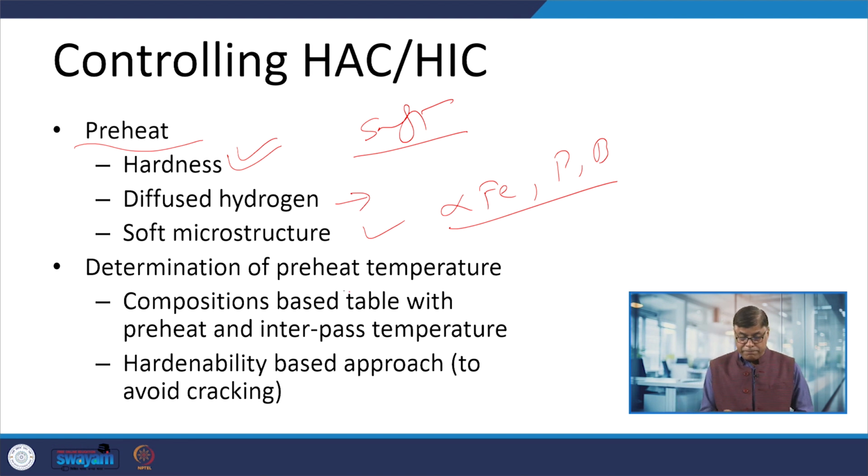So, the preheating is very crucial in that way, because it is not just promoting the soft phase formation, but also helping to reduce the hardness and reducing the hydrogen level. So, all these three things will be favorable with regard to the control of hydrogen induced cracking. So, the preheat is very crucial.